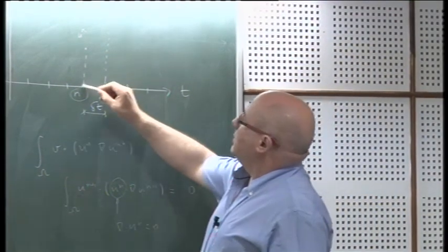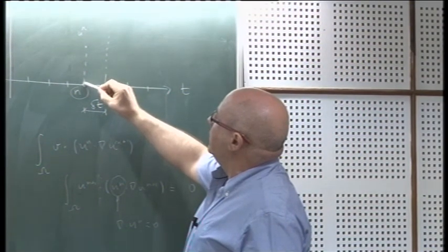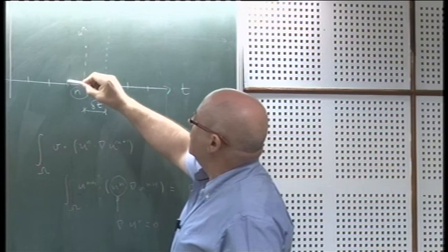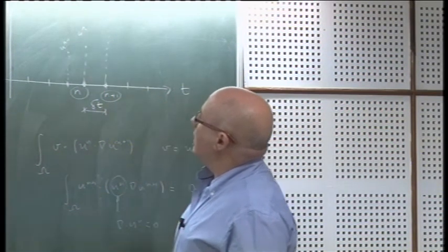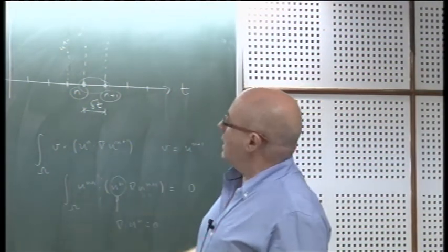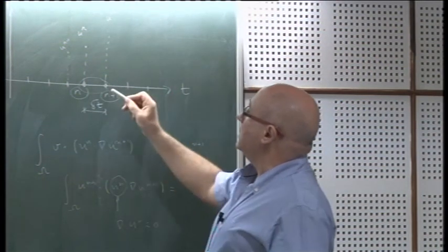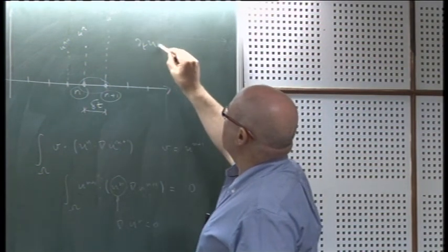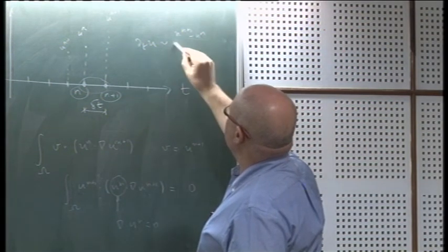The way to obtain a second order scheme is to obtain an approximation of the advective term using the velocity here and the velocity here, so u^n and u^{n-1}. Okay, that's a single step scheme in the derivative. You take the derivative only here, but you use previous values of the velocity, not in the derivative. The derivative is approximated as (u^{n+1} - u^n) divided by delta t.